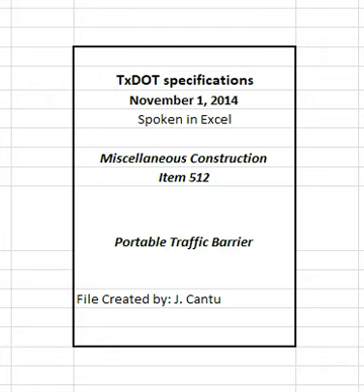The engineer may approve the use of the product if the barrier sections substantially meet typical cross-section dimension requirements, there is no evidence of structural damage such as major spalls or cracks, the general condition of both the barrier sections and their connectors is acceptable, and the barrier is new or the barrier is being reused.